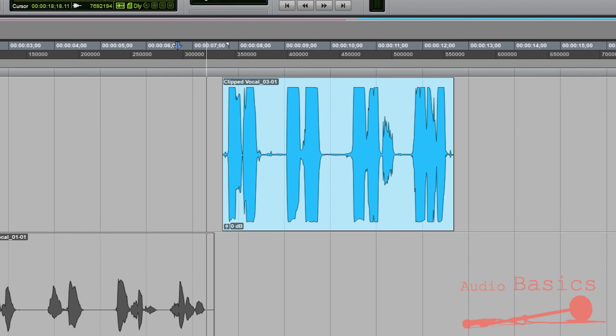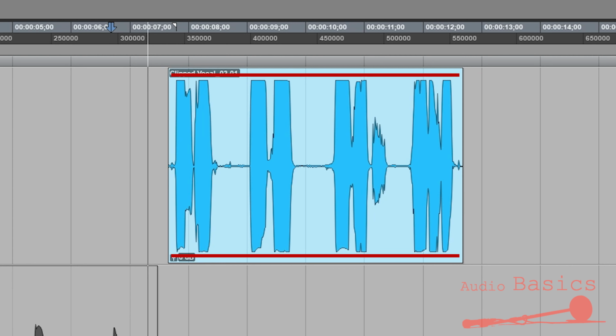You've probably heard this or similar sounds on podcasts, YouTube videos, or live streams. This sound usually means that the preamp for the microphone is being overloaded with signal, and as such cannot take any additional volume. So it cuts off the waveform from any more dynamic range. I'd like to point out that talking into your mic and shouting into it will give you drastically different signal levels, so it's important to adjust your preamp settings accordingly.